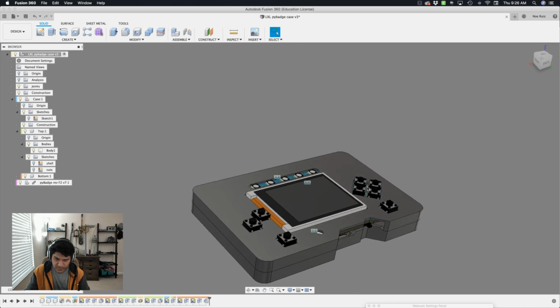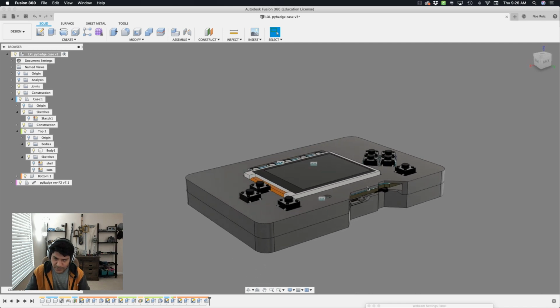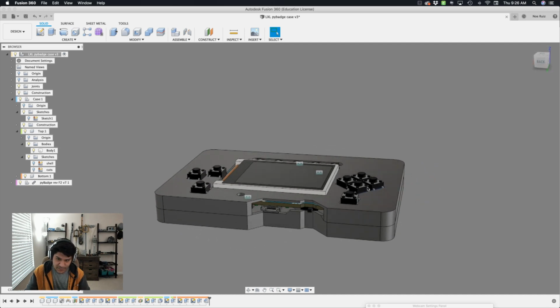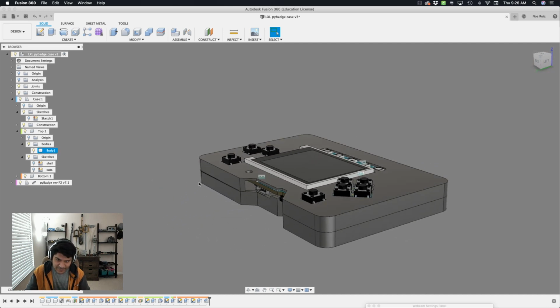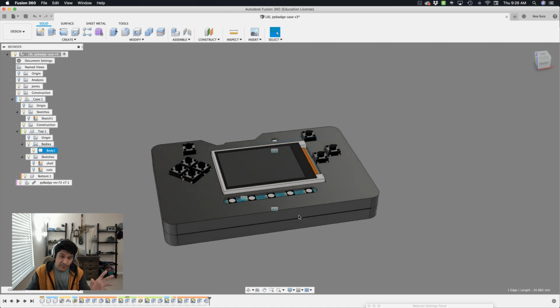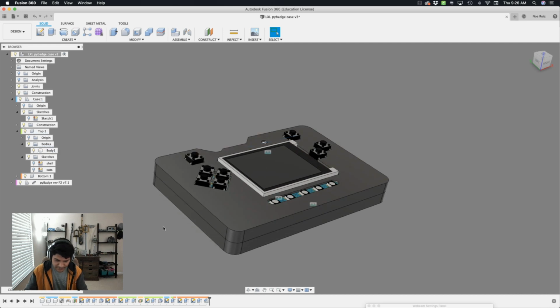That's pretty much a good stopping point for part 3. In part 3, we can start doing the snap-fit features. We've got to be a little bit smart with it on this edge. We're going to have to create some snap-fit features that have custom lengths because these two are different lengths. For the left and the right sides, however, we can just use a mirror. So once we apply it to one side, just mirror it to the other side. That's going to work out pretty good. Well, let's go ahead and save our stuff. And obviously you want to add a better comment than that, but hey.